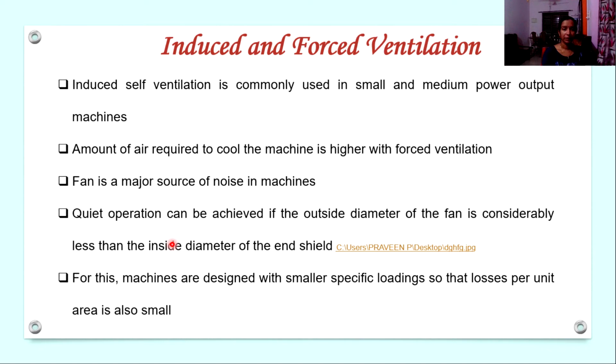Now, that means the outside diameter of the fan should be less. That means we have to use a small fan. If that fan is small, that means that the temperature rise in that machine should also be less. Then only we can use a small fan.